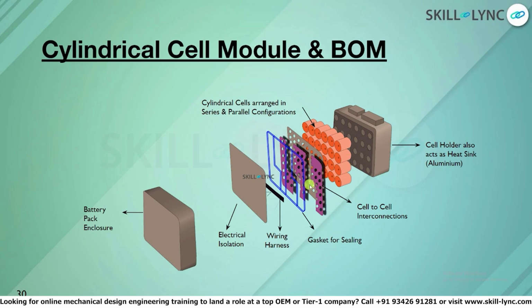These are the nickel bus bars used. Over here, this brown portion acts as an insulator, so that these bus bars do not touch the cell body, because the cylindrical cell casing is a metal body. It's a metal can, so you insulate it first, and only the required portion is exposed, and that is where you connect the bus bars and weld them.